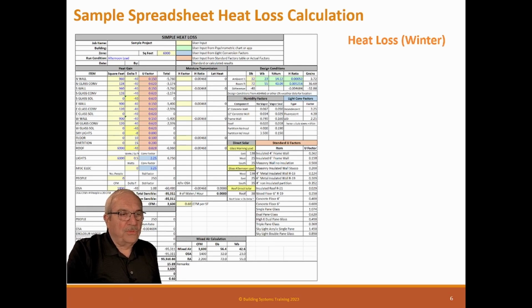Years and years ago, we used to have a design philosophy in our, I'm in the Southwest, so I have real mild temperatures, where we were having big office buildings that they heated with the heat of the lights, because the lights were 2.5 watts a square foot, so they have a lot of heat. So they just leave the lights on all night, and that would heat the building. Well, then the revolution came, and we went to T8s and the T5s, and then the LEDs, and those buildings were no longer heated. So I had to come in and retrofit supplemental heat because it took a lot of heat out of the building.